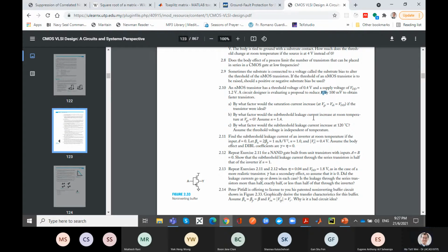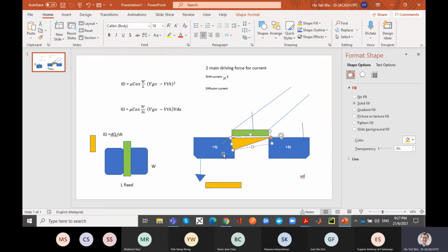Okay. All right. I'll go to sub-threshold leakage a little bit later. So I just want to finish up on this one here, since we're talking about this one. Now, this is what we call the long channel equation. Why? Because it's an ideal MOSFET. It tends to hold for 1 micron feature size, lambda equals 1 micron and above. That means very, very old technology. Nowadays, today you have 7 nanometer, almost 1,000 times smaller in size.